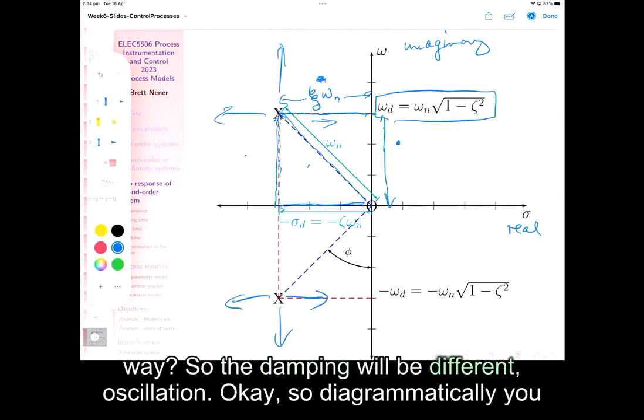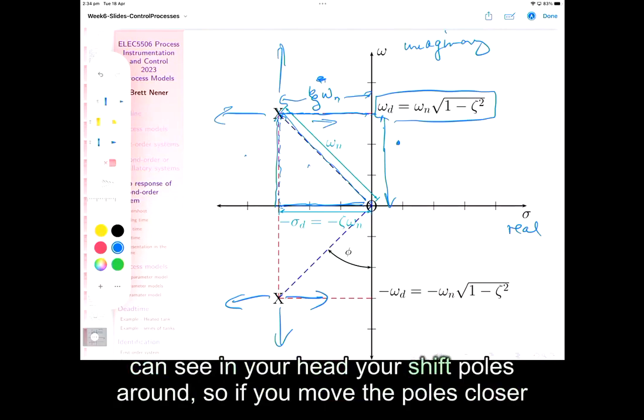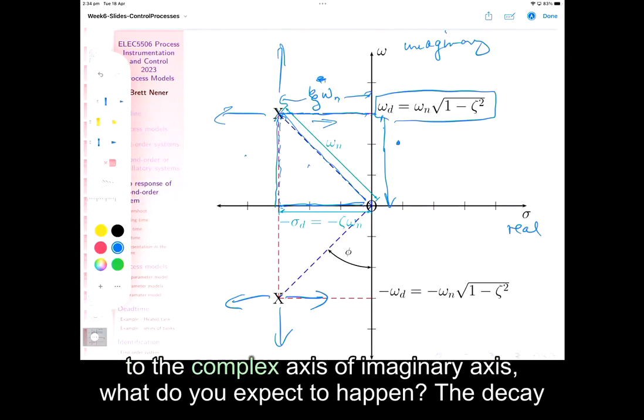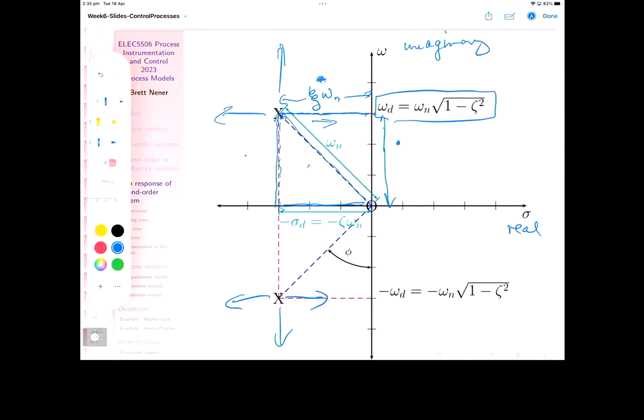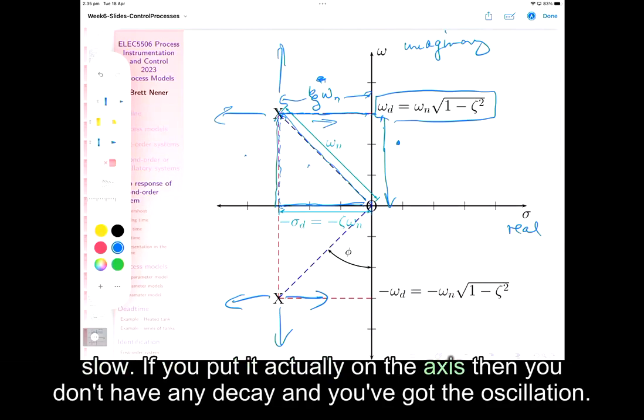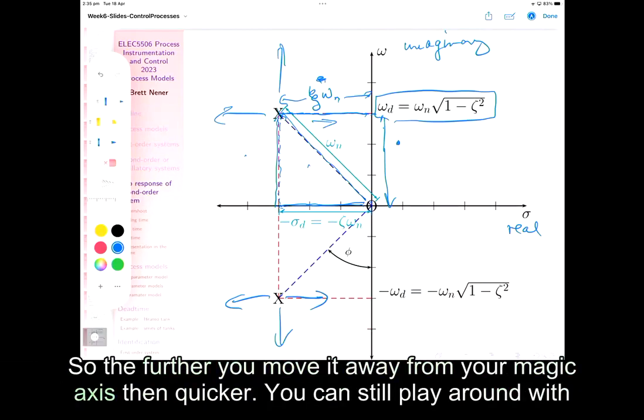So the damping will be different, oscillation. Okay, good. So diagrammatically, you can see in your head you shift poles around. If you move the poles closer to the imaginary axis, what do you expect to happen? The decay rate is going to be gradual, isn't it? Yeah. The sigma is getting smaller. The rate of decay is quite slow. If you put it actually on the axis, then you don't have any decay, then you've got the oscillation. So the further you move it away from the imaginary axis, the quicker the decay.